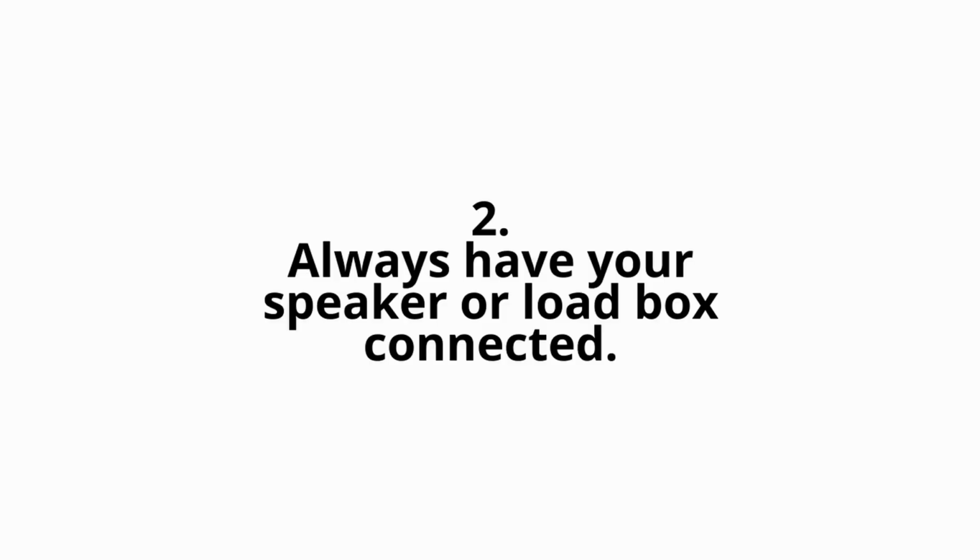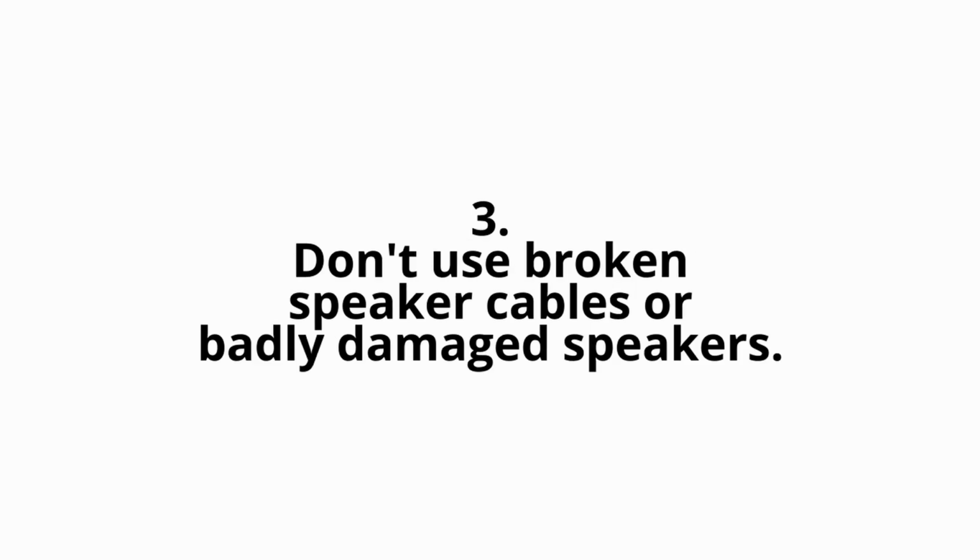2. Never turn your tube amp on if there is no speaker or load connected, especially when the amp is seeing an input signal from your guitar or some other source. This could result in the amp seeing an infinite impedance, and this could be harmful. 3. Never use broken speaker cables or anything that could end up short-circuiting. This would be like having a zero impedance, and it could end up damaging your amp.